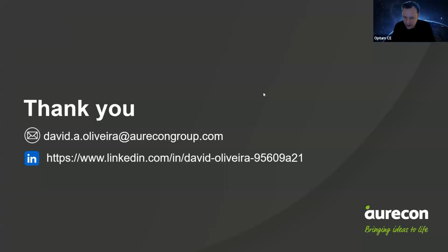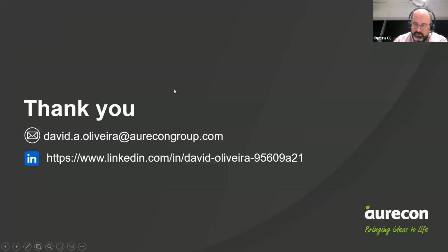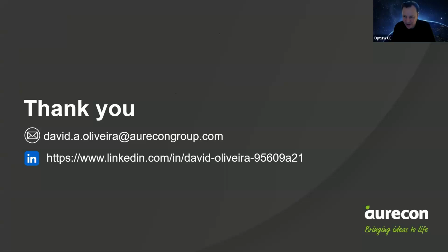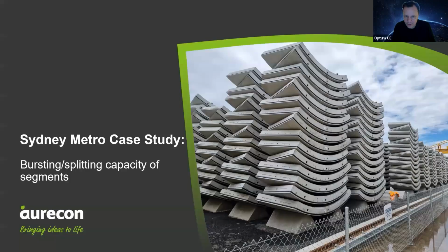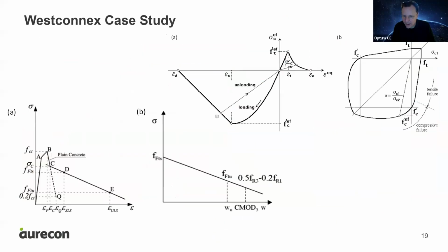Yeah, I will answer the question by Reza here. It says, slide 19, how was the improvement of constitutive behavior of the steel fiber reinforcement due to confining pressure shown? I might go back and show the failure surface. I think you show a failure surface which is relevant for plane stress, but I'm assuming you use some sort of general 3D Mohr-Coulomb type.